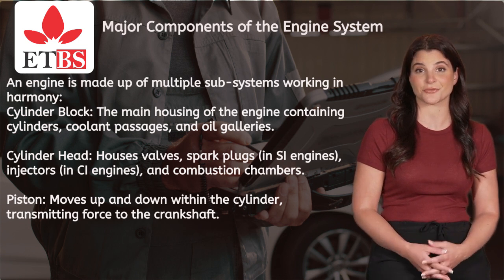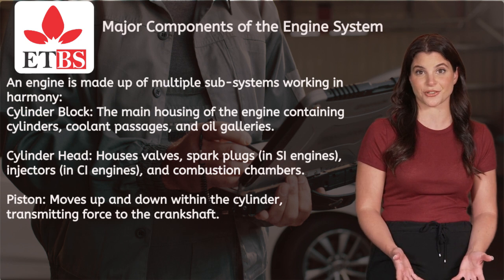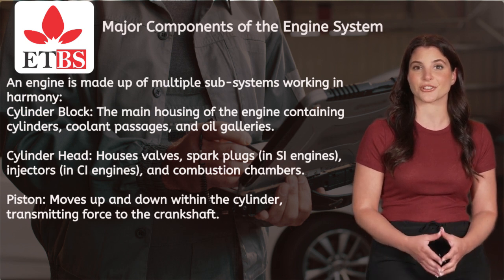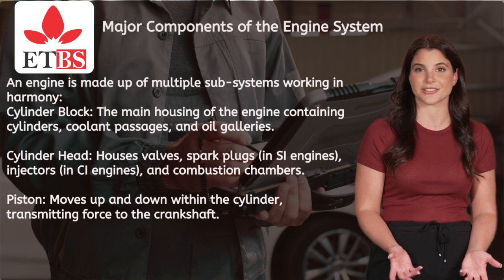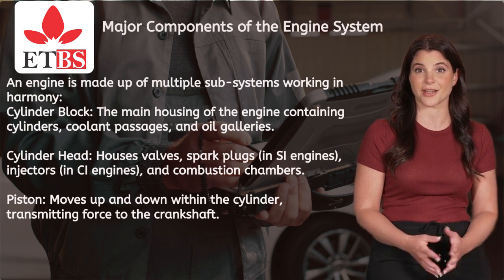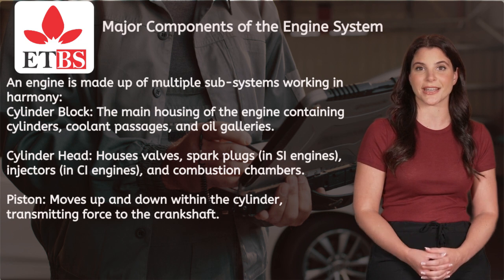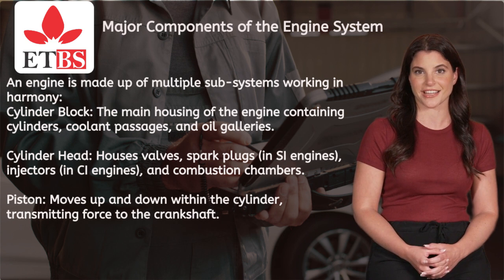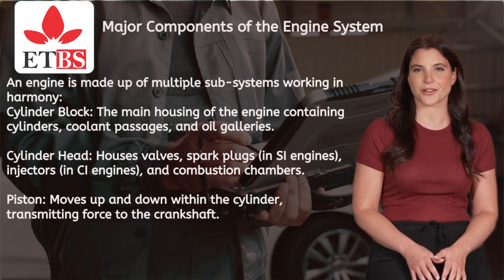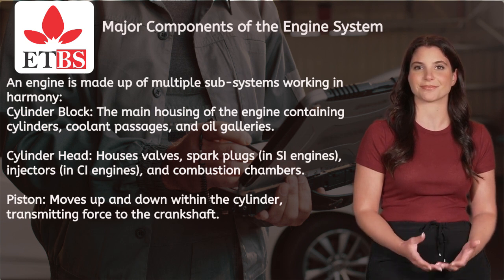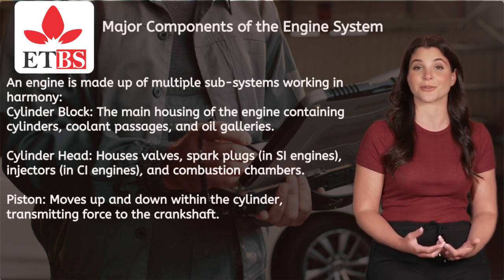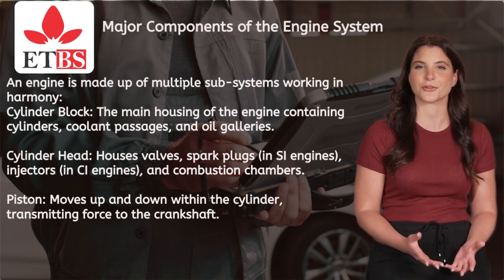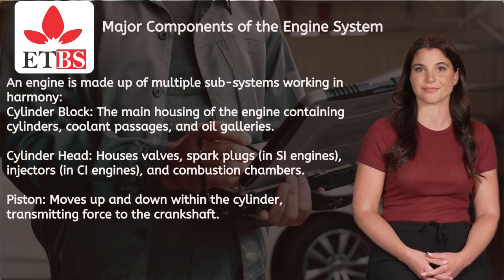Crankshaft, converts reciprocating piston motion into rotary motion. Camshaft, controls valve timing for intake and exhaust. Valves, intake valves admit air/fuel mixture. Exhaust valves release burnt gases. Flywheel, maintains engine momentum and smooths out power delivery. Lubrication system, oil pump, sump, oil galleries for friction reduction. Cooling system, radiator, water pump, thermostat, coolant channels to maintain optimal temperature.